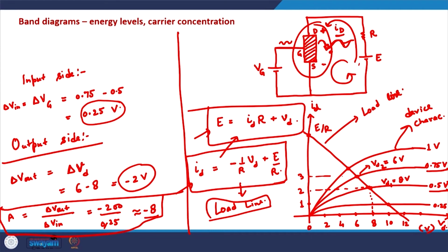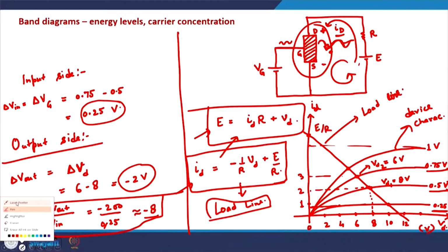Okay. Similarly, the switching can also be understood from this plot, although switching is clear from the device design as well. At 0.25 volts, let us say, when the gate voltage is 0.25 volts, the current across the device is very low, and when the gate voltage is, let us say, 1 volt, the current is extremely high. So just by changing the gate voltage, we are able to switch from a low current state to a high current state. We are able to switch on the channel in the device so that the current can flow.